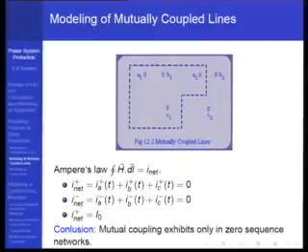For example, in load flow analysis, people will give you one circuit, two circuits, three circuits. They will never specify coupling between them because it's negligible. That's probably one of the reasons why you can go and stay close to a transmission line without worrying about the magnetic fields, because provided it is nearly balanced, the magnetic field outside of it is not going to be very significant. You can go and live there, as there is not much magnetic field there, provided it's balanced.